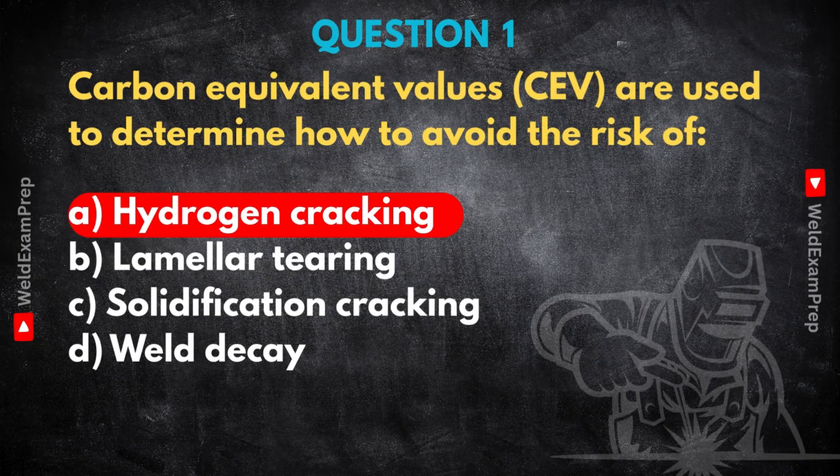And those brittle zones, they become prime spots for hydrogen embrittlement. The hydrogen basically makes the steel even weaker, more brittle. And that's where the cracks start. Often delayed cracking, too. Sometimes hours, even days after the weld looks perfectly fine.